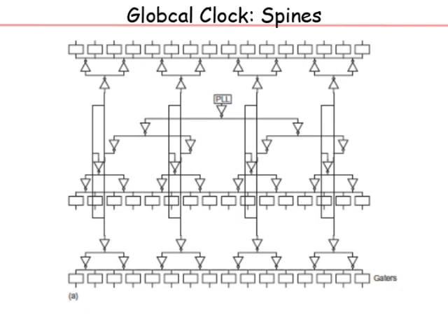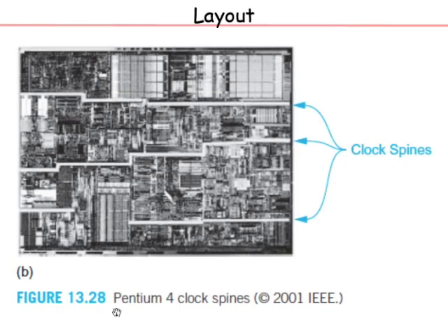So in fact the lowest clock skew is achieved, and this is done in extreme cases when you really want to keep the clock skew very small, is to actually have a large metal grid. Just take this concept of these horizontal spines and imagine that you have this grid of horizontal and vertical wires, and all of them are shorted together. This grid is like one large, very low impedance. Maybe you make it with very fat, very wide wires, from an upper layer in the process, so they are also very thick. So you have very low impedance.